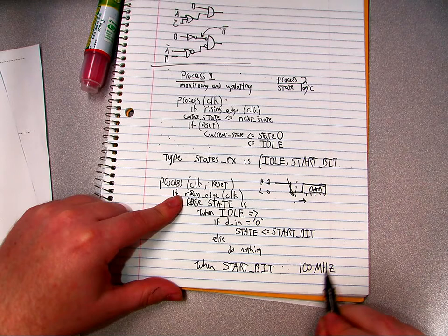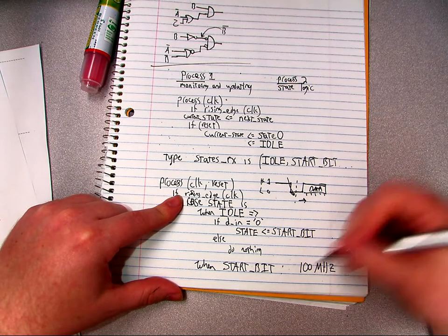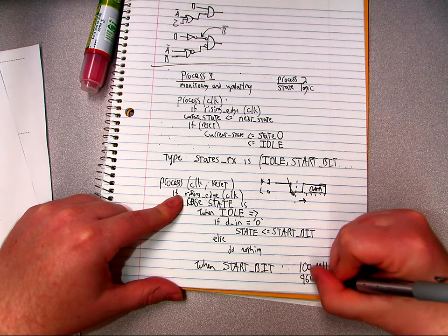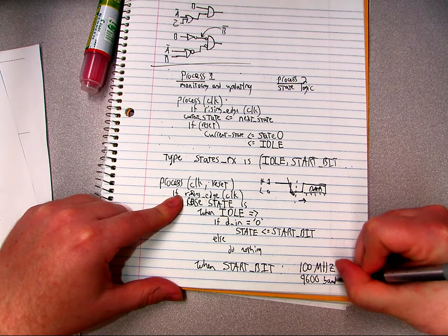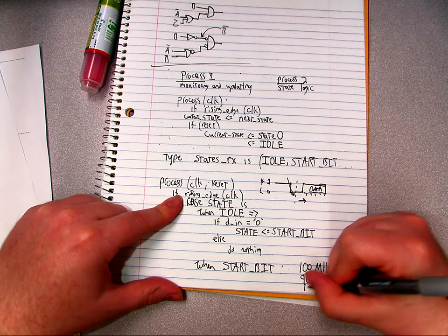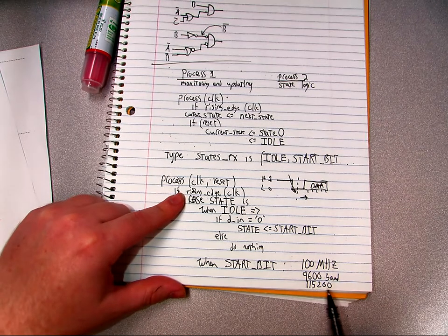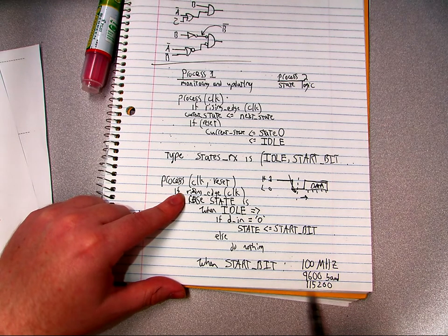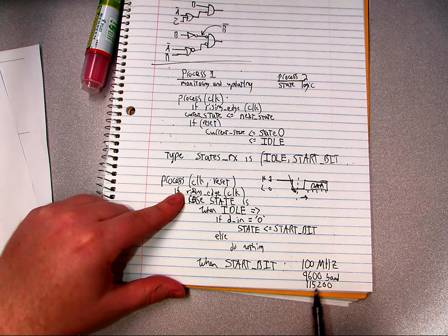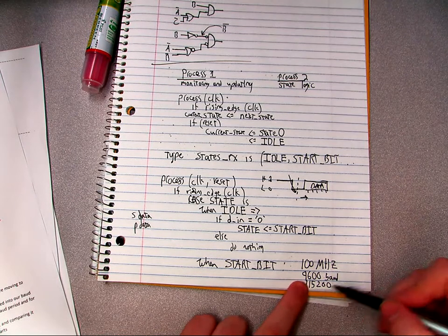What we need to get that down to is your baud rate, whether that's 9600 baud, or I like to use 115,200. The reason I like to use this is it simulates better, because I don't need as many main clocks in order to sample down to this level. But 115 kilobaud is still slow enough that it works really well on boards. But you can choose. You really can, as long as you do the math right.